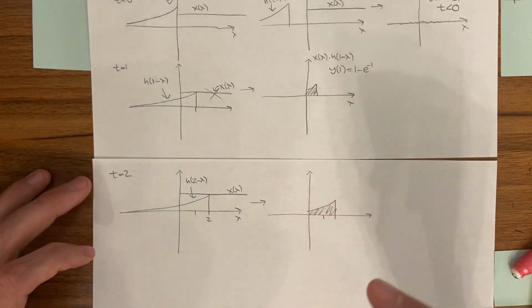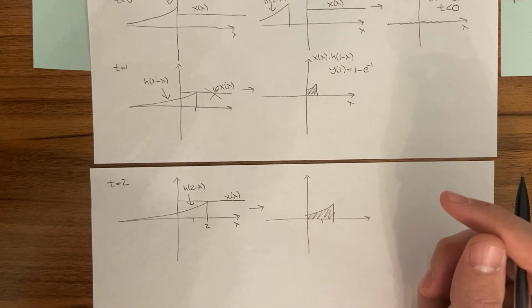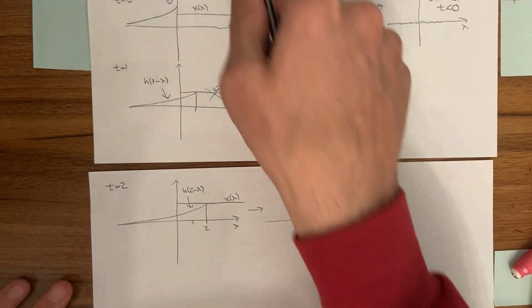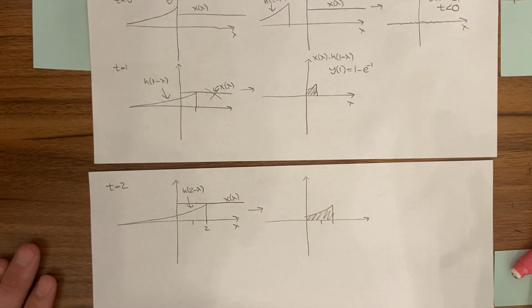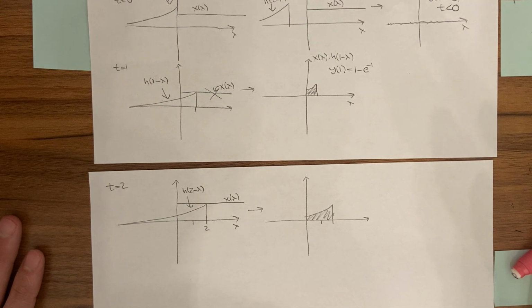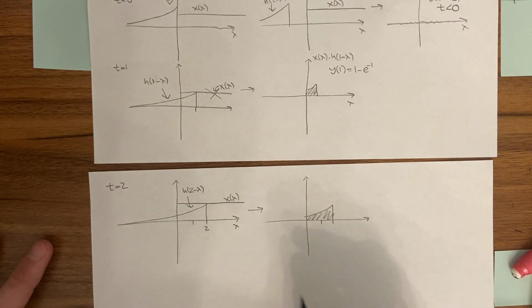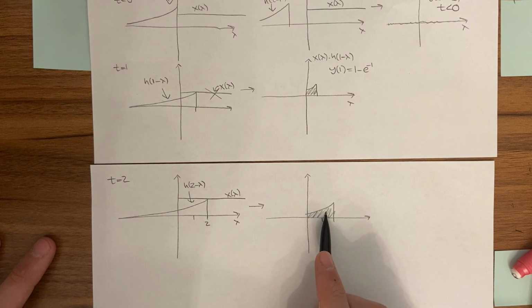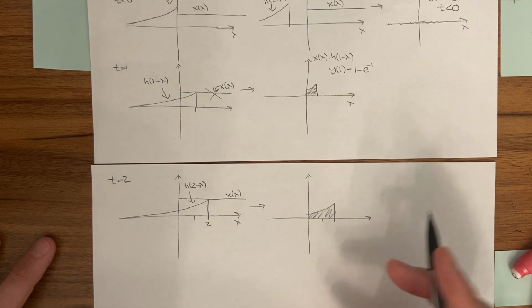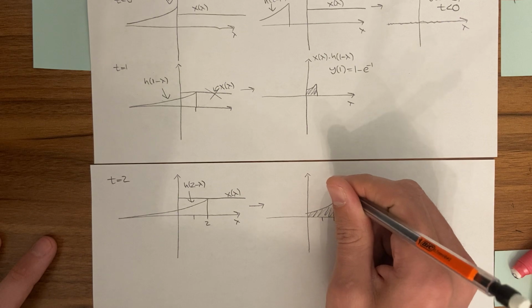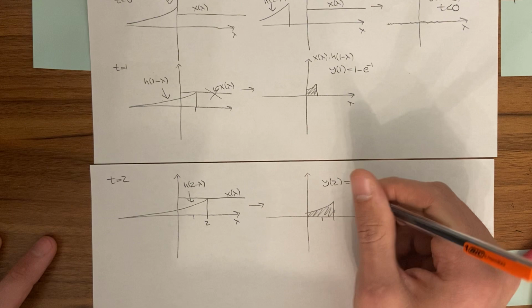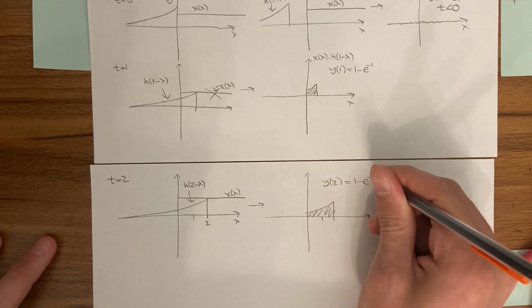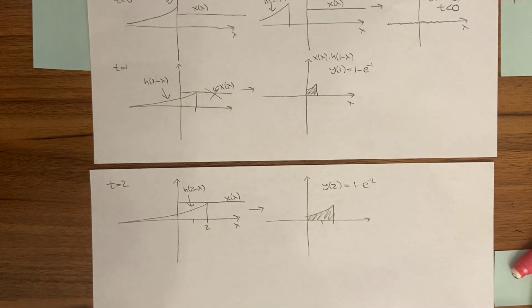So essentially with convolution, what you're doing is you flip one function. In this case we flipped e to the minus t u(t), and then you start dragging it. For each incremental drag, every time you move it, you end up needing to multiply the two functions together and then integrate, okay? So this would be y of 2, which would be equal to 1 minus e to the minus 2, okay? Okay, cool.